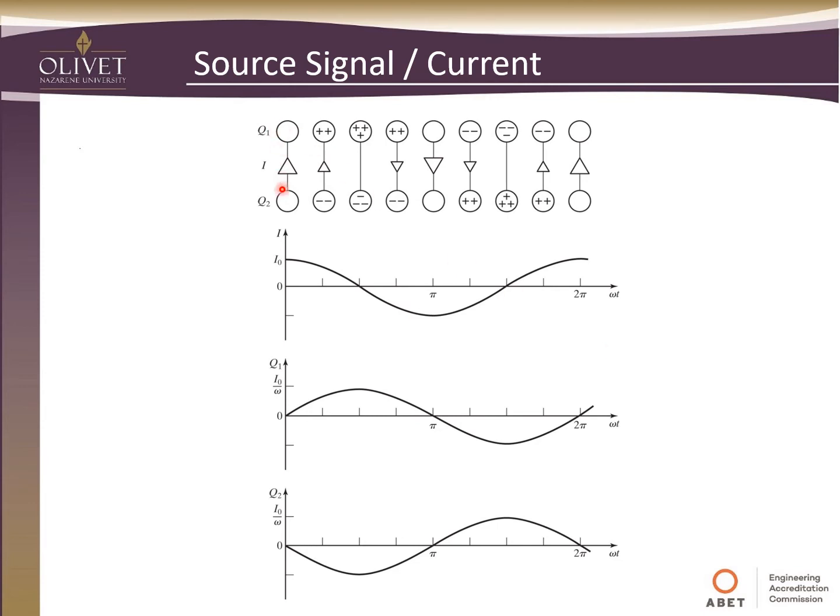And then you can think of it in terms of the charge. As there's no charge at each end of our antenna, the current's maximized, as the charge is flowing from one side to the other. But as the charge builds up at each end, we see that the current starts to decrease until the maximum charge is at the ends, and then there's no current there theoretically. That's why there's a zero here, and these are maximized. So this little graph at the top is showing you what's going on in our infinitesimal antenna.